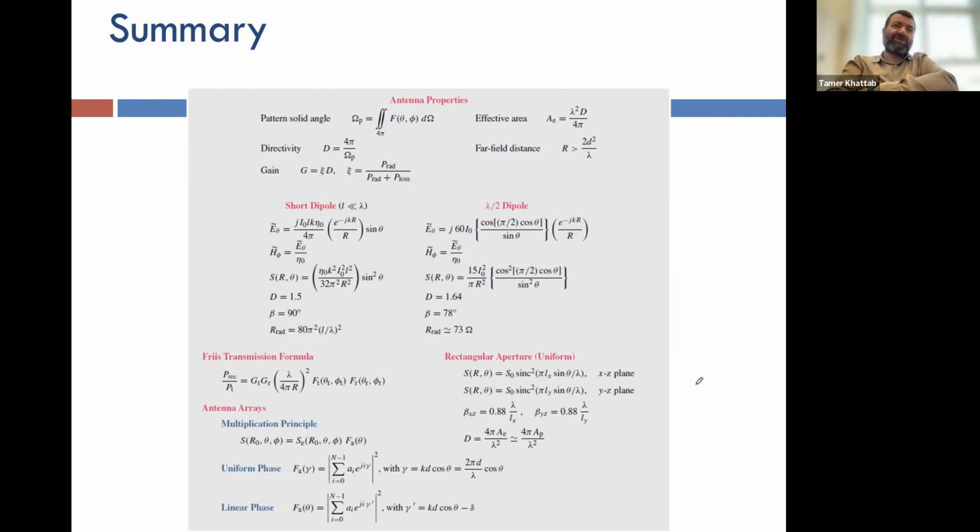You take those factors, you can plug them into the power budgeting equation to do some kind of analysis. How much power do I need to inject in the transmitter in order for the receiver to be able to process the signal, or in order to receive at least the sensitivity amount at the receiver side? And then accordingly, this can affect your power amplifier design, the quality of your electronics, if you want to make sure that you receive lower power signals and so on.